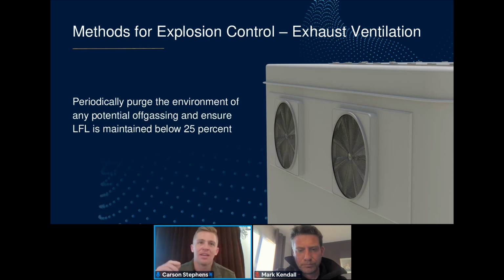And so the idea is, hey, we're going to turn on this fan every 60 seconds and purge it for 10 seconds. It's kind of a rudimentary way to reduce the risk of an explosive atmosphere, but it's an effective one. It's one that's easily understood within the industry, so it's an easy one to implement, and it's one that normally a project has at its disposal.